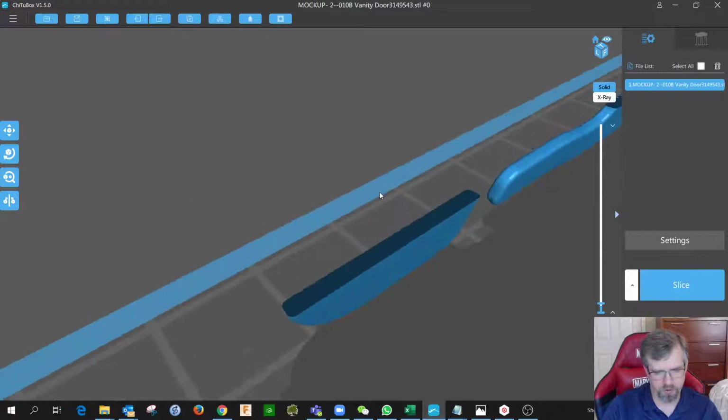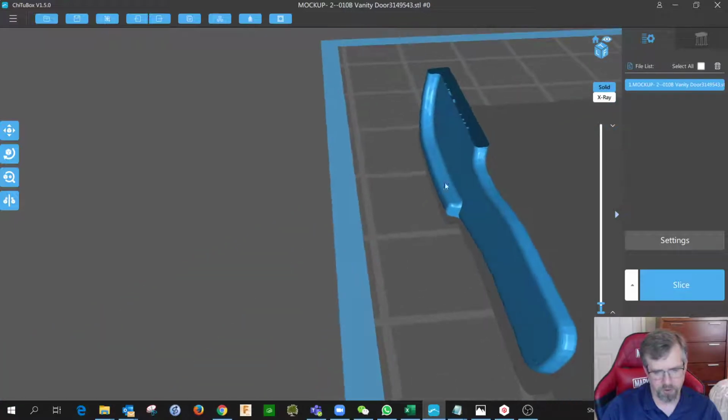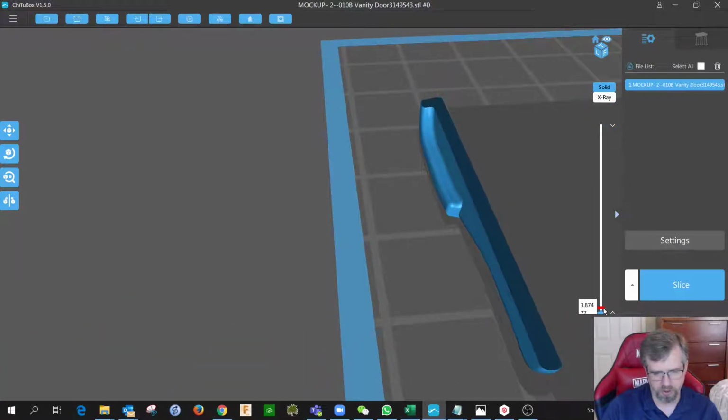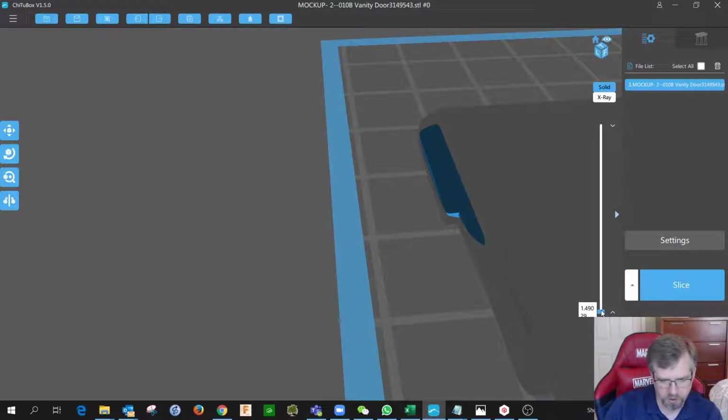With that in mind, I want to come back here and show you on this part where I think there is a very small example of that issue. If we start going, once I'm doing this movement, I can click the up and down arrows on the keyboard to go layer by layer. You can see this is the distance, in millimeters I believe, that I'm up, and then I'm clicking the down arrow, layer number 41, down, down.